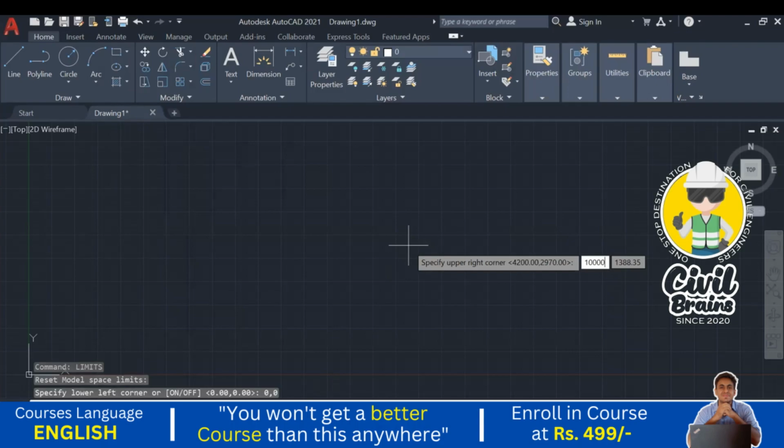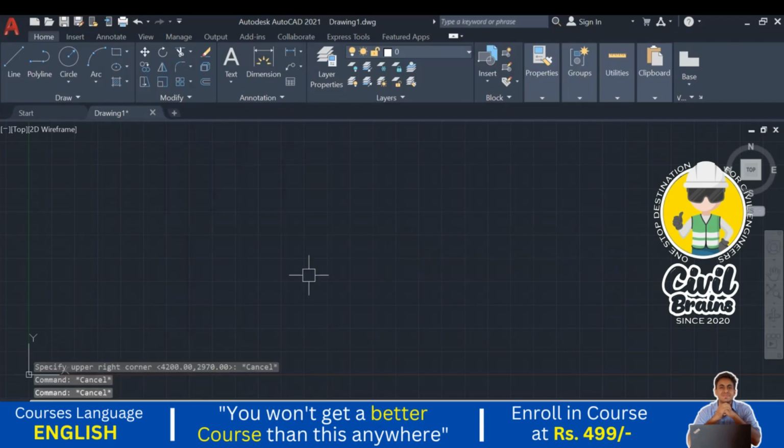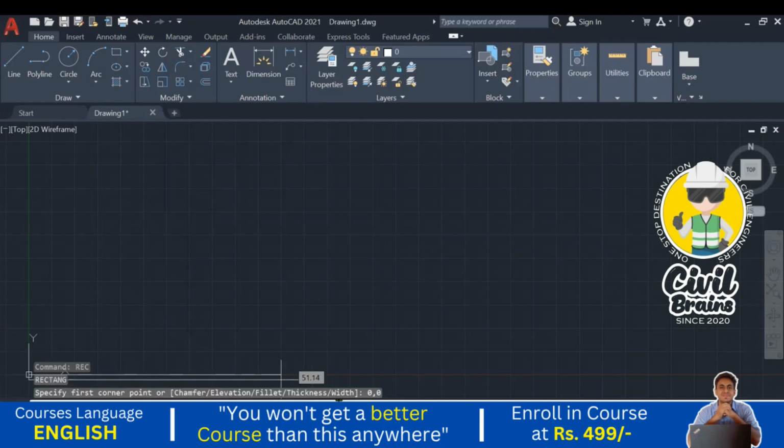I just type here, you can type anywhere. Okay, sorry. Limits 0, 0. I type here 10,000 comma, for the height 3,500, just take 5,000. Okay, enter. So next rectangle, enter, 0, 0, enter. Whatever we have taken, the same dimensions we just take.